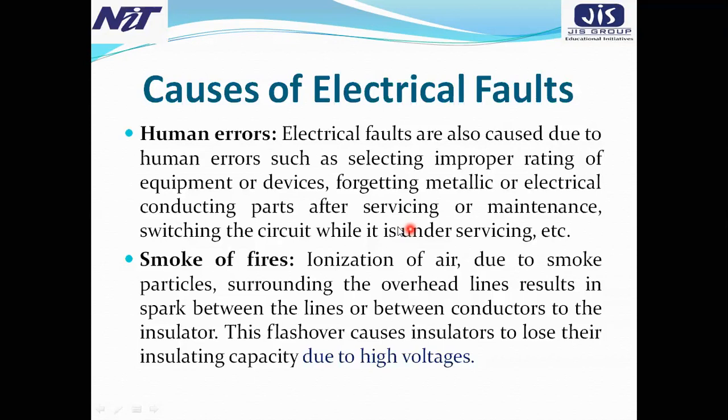To avoid the human errors, there are some special devices. The lifeline detector is also used in the system to avoid human errors. Like when some transformer fault is there, the engineers, after disconnecting from the substation or from the distribution station, suppose the line is isolated from their control panel, but the charging current stays inside the cable.